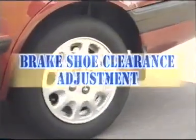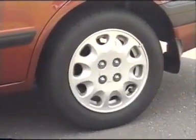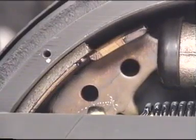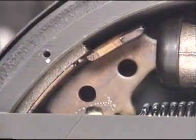Excessive clearance between the brake drum and the lining will reduce braking speed. If too small, the brakes will drag. If different at each wheel, the vehicle could be pulled to one side or fishtail.